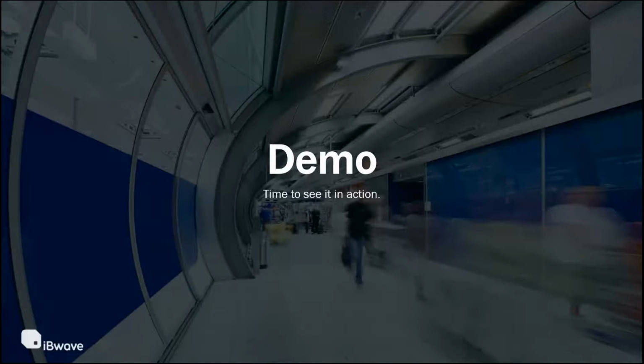So if you have an area with weak coverage and you have no points in that area, and then the interpolation from something like a room next to it or the corridor next to it with good coverage, yes, the interpolation will bleed and show like there is good coverage there, but inside this room, it might not be good coverage. That's a challenge. So either define an interpolation area and say, okay, don't consider this area because I don't have data, or you have to go get the data inside this area.